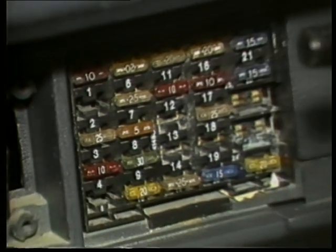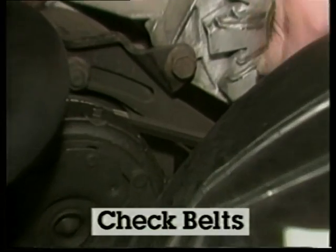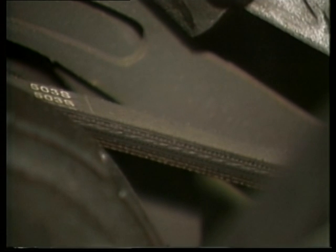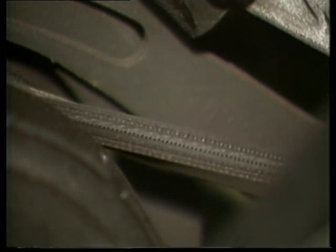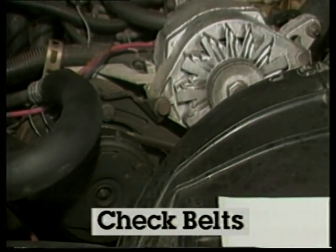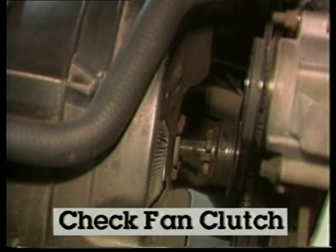To begin your inspection in the engine compartment, check the compressor belt. It should not be broken, frayed, or slipping. Adjust belt tension if needed. Check the general condition of a fan clutch if used. It should have some resistance when rotated and not show signs of fluid leakage.